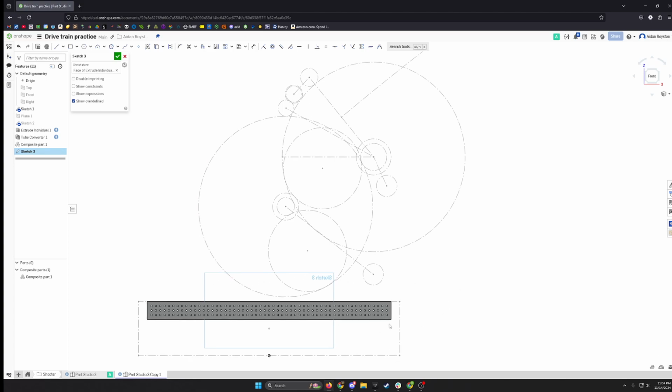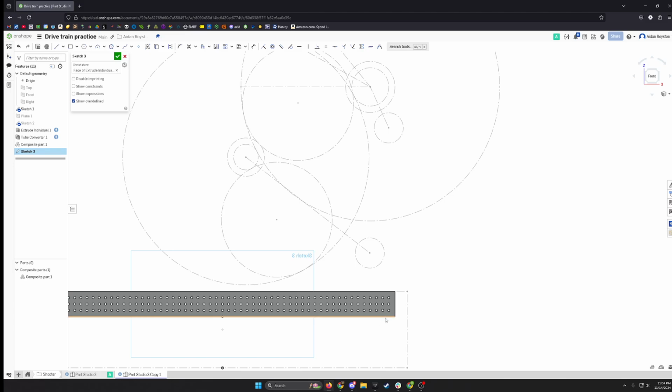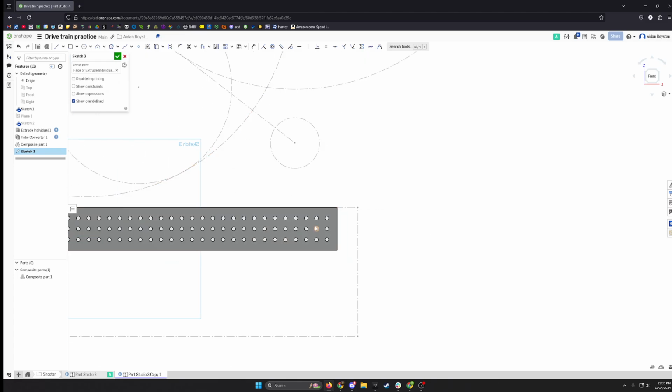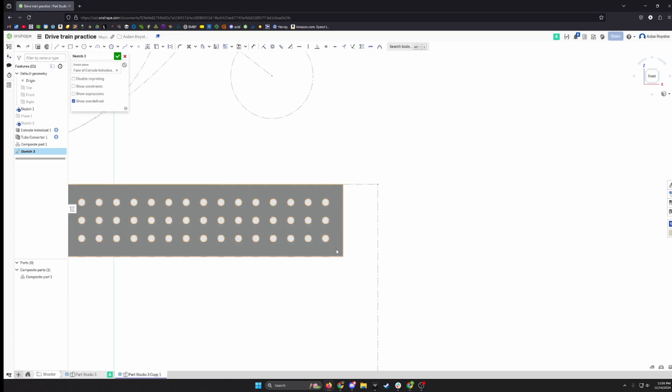The first thing we're going to do is that we have all these holes in this bar, and this is what we're going to mount the plate to on the frame. And so we have to have holes in the plate to mount it with. So we're going to make our first hole, and instead of having to make a circle and dimension it, we can go up here to the project convert tool, also called use, or hit U, and just select the circle.